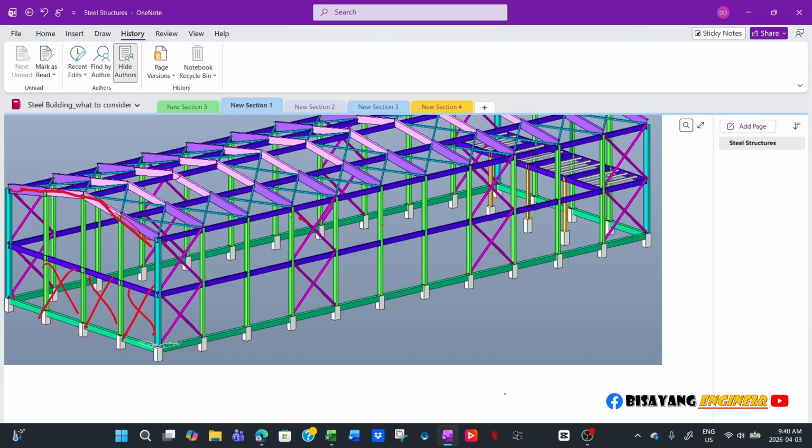What he meant is, since there is no room for cross bracing here because this is an overhead door, these three openings, he can only put cross bracing in this area. It's not allowed because it's not symmetrical. Like I said, no. If only one bracing is required, then so be it. All you have to do is transfer that. As long as you have the proper load path, that's the most important.